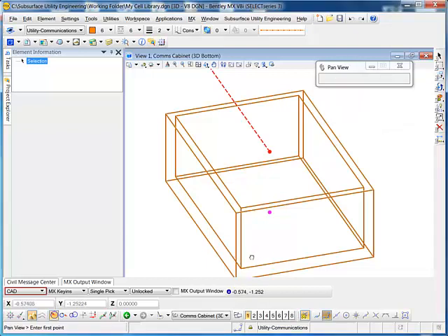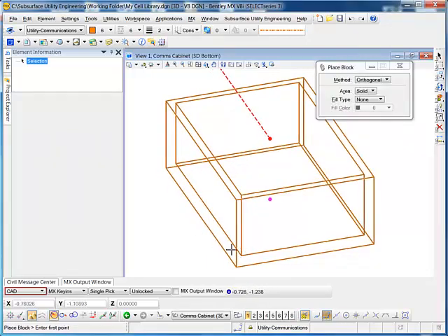So with that in mind, I'm going to press F11 again to wake up AccuDraw, and I'm going to hover over the inside corner here and use the O key to set the origin. I'm now going to use the side key to rotate the compass around, and I'm going to move in maybe 0.1 of a metre, something like that.